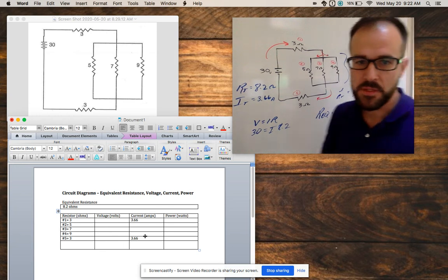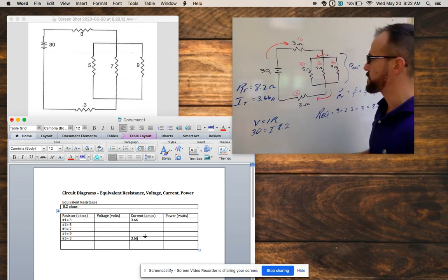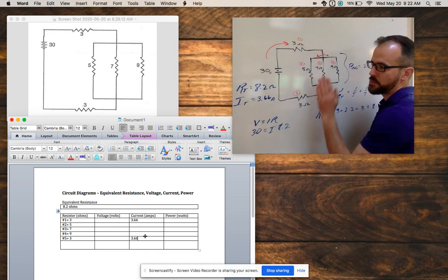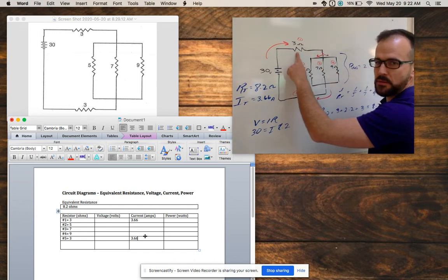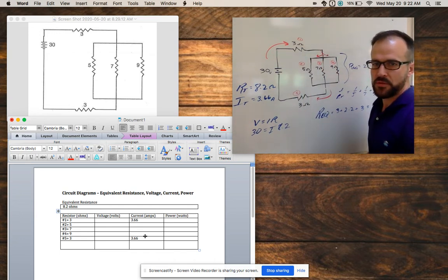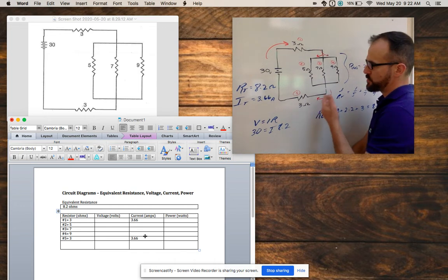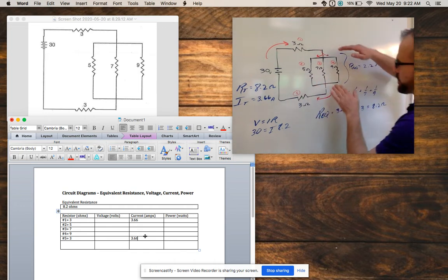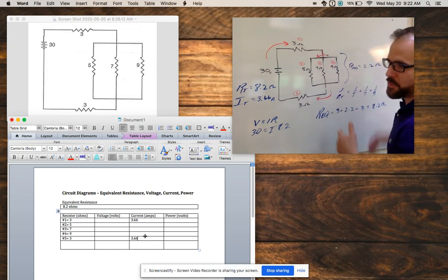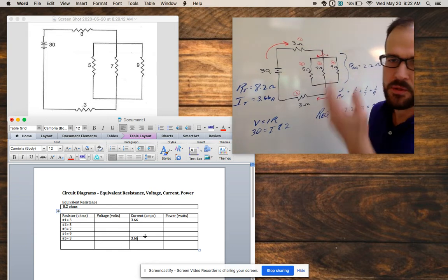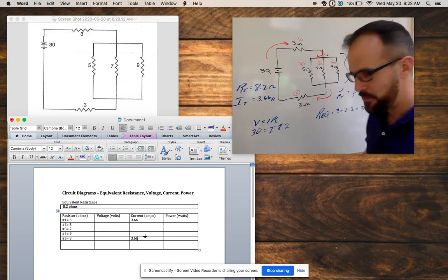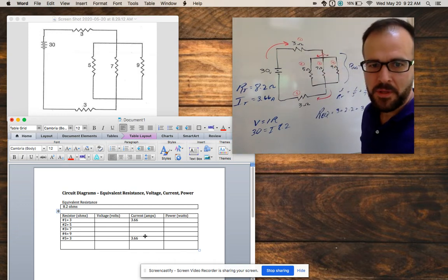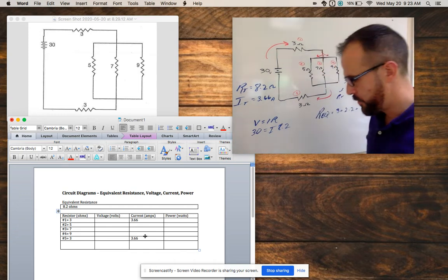So what do we know then? Next up, let's find the voltage drops, because now something else to remember is things in series have different voltage drops. So it'd be easy to find it here with Ohm's law, V equals IR, and then pretty easy to just see what's left, and that would be the voltage drop for all 3. Things in parallel all get the same voltage drop, and then we'll be able to solve for the I's going down each branch. I don't know if this is becoming any easier or more clear, but hopefully it is. Let's see. So voltage drops. Let's do that.